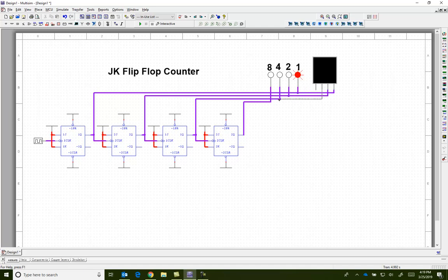When I start my simulation, my counter will be counting forward and the hex display will translate into hexadecimal, meaning that after 9 you'll see A, B, C, and so on. When it reaches F, or 15, it counts again starting from the starting sequence, which is 0.